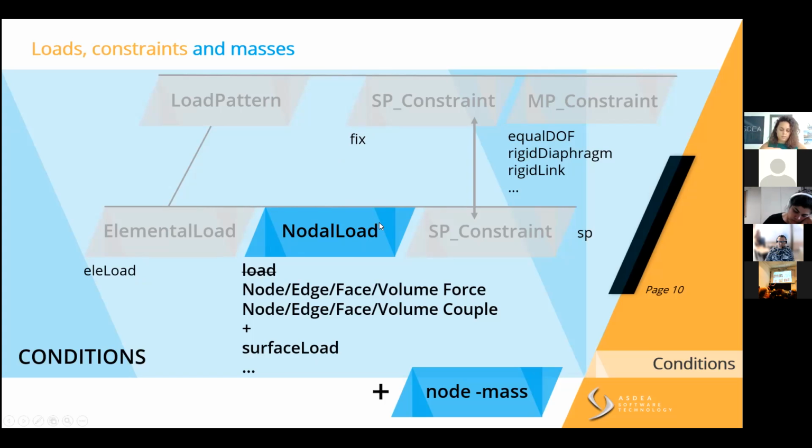This is because, taking a step back, we're doing finite element modeling. Our loads are assigned to the nodes. This we all know. And there's just a special case in which loads are integrated on the beam length, because we know that the element we're applying it to is a beam. So in OpenSees, they created this command that we can use to define a linear load instead of a nodal one.